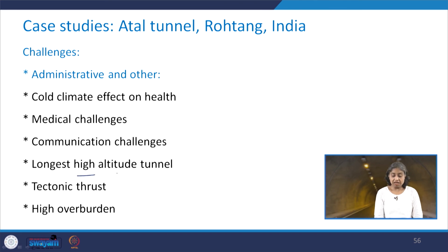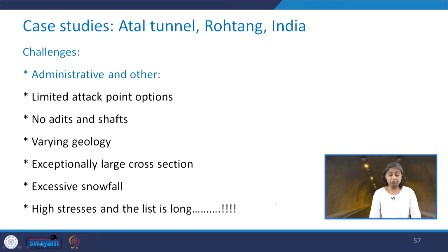Longest high altitude tunnel, there were tectonic thrusts which were posing problem. I mentioned that high overburden posed the problem. Then you had the limited attack point options because of the difficult geology. There were no adits and shafts and extremely varying geology here.